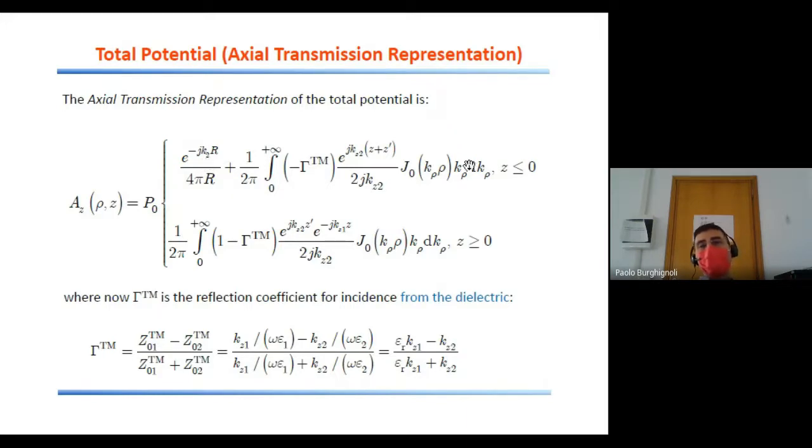And then there is the reflected wave, which is not available in a closed form, but it is represented as a zero-order inverse Hankel transform. So you can see the kernel of the transform, that is the Bessel function of order 0. Then there is the one-dimensional Green's function in the lower medium. And finally, there is the current reflection coefficient minus gamma for TM polarization.